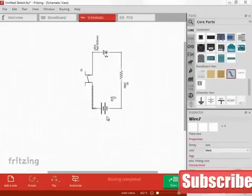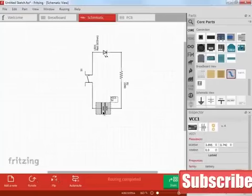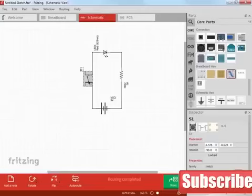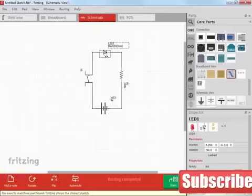We'd like to use a 9-volt battery, and the library defaults to a 3-volt battery, so we'll go to the properties for that. We'll select our 9-volt battery. Our switch is either through hole, THT, or SMD, which is surface mount. We'll leave it at THT, which is through hole. Our diode, we can leave it as 5 millimeter through hole, or, let's just for fun, put it 3 millimeter through hole.